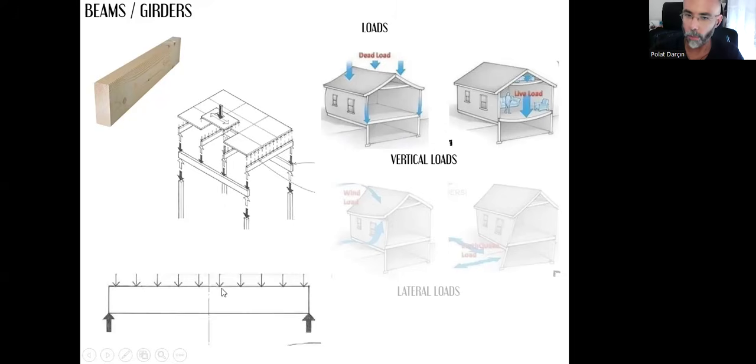So this is the upper part where the floor is attached to the beam, and the loads of the floor are applied over this upper line. And there are two columns that support a beam in these ends. And because of these columns, there are two opposite direction loads, this time upwards.